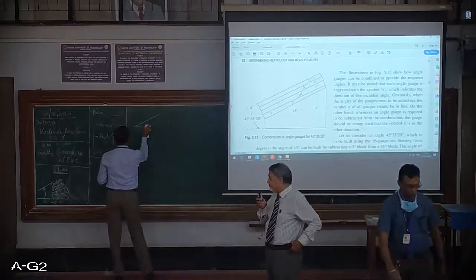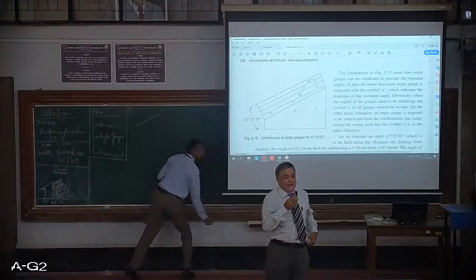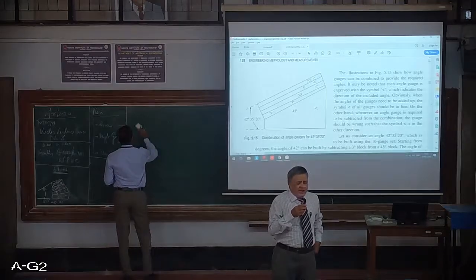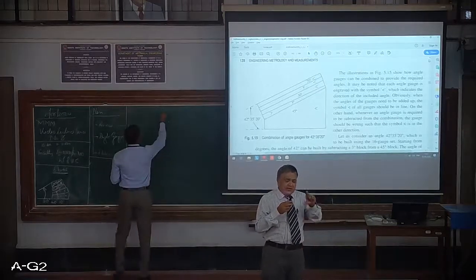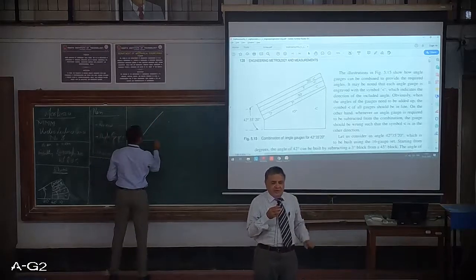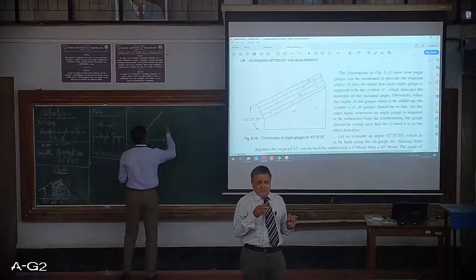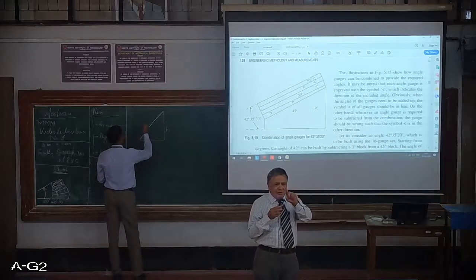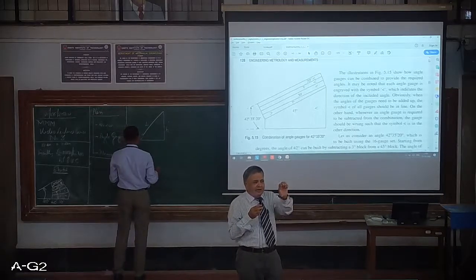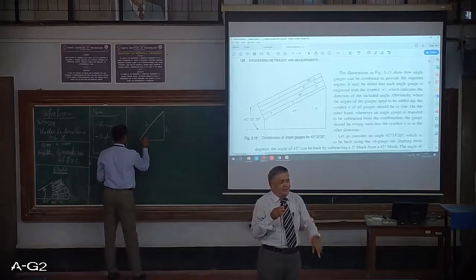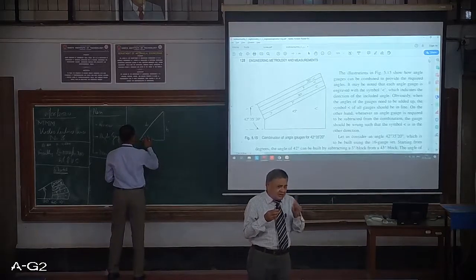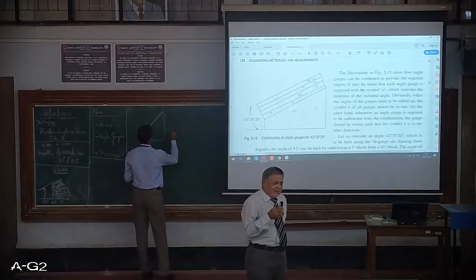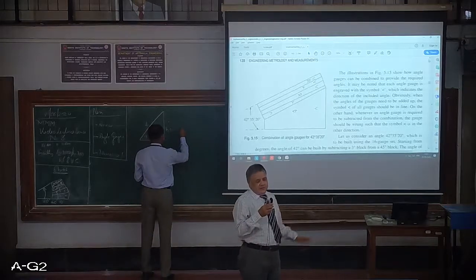One more interesting topic: you may ask me, can I build an angle of 120 degrees? Yes, as I am talking from a commercial point of view, not an academic point of view. Commercially, the angle gauge set is available with an additional block of 90 degrees. But it will not be a standard component. You will have to purchase it as an additional component. If it is 120, 120 minus 90 is 30. So on the 90 degree block, you will have to make the 30 degree. It will give you 120 degrees. But it is an additional accessory, not a standard part of the angle gauge set.